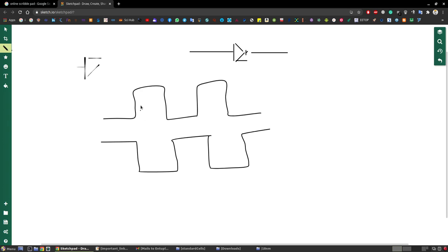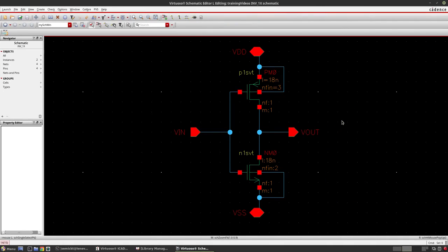It is just one input, so I can give one pulse, say with a pulse width of around 10 nanoseconds, and I can have around 5 cycles of this. So for how much time do I need to run? 10 nanoseconds times 5, so it will be 50 nanoseconds. Total simulation time is 50 nanoseconds, right? So we'll see how we are going to do that.